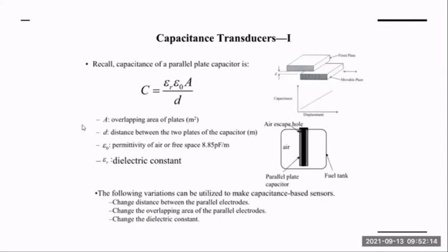You set the computation to the dielectric of air, for example, as usually in factories, and then there is an object in between the two plates, for example a bottle filled with water. So the dielectric changes. Instead of air, there will be water in between. So the capacitance changes. According to this change in capacitance, you can set or calibrate the function you want the system to do.